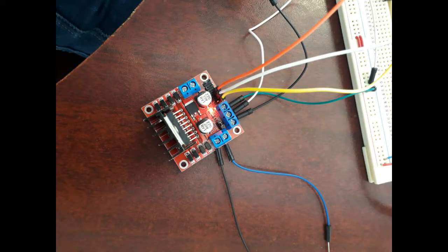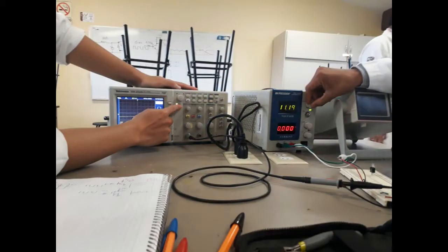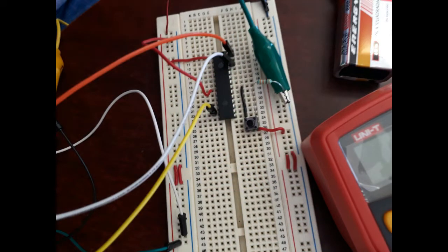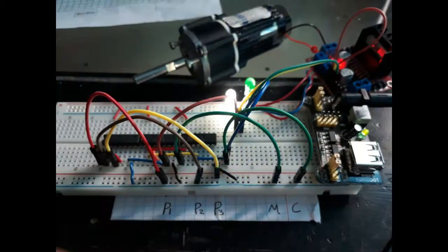In this practice, the device did not work in the physical circuit, although in the simulation it worked perfectly. The same result was not obtained in the first part. This is also explained by the connection of the PIC. A small cable was used in the voltage input for the PIC, and there was a bad connection on the bright edge.